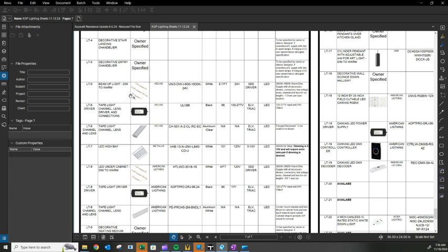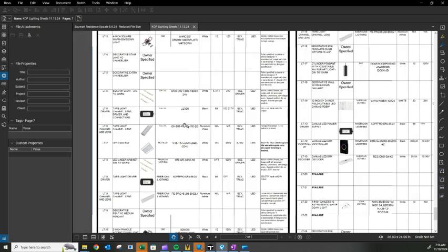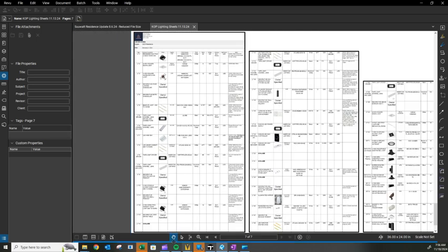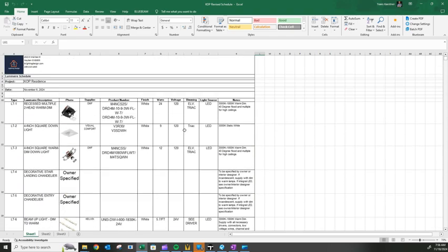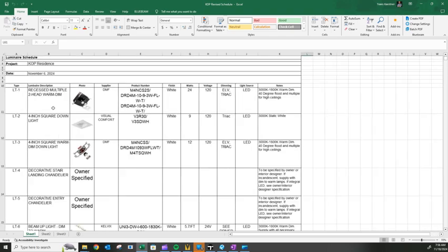But then on the other lights, we're looking at mounting details, color temp, optics, voltage, and specifying what's called the nomenclature, the part number, to make it all work with the project, like the ceiling types and the mounting it needs. We do that in this Excel file, and then we upload it onto that drawing after it's done.